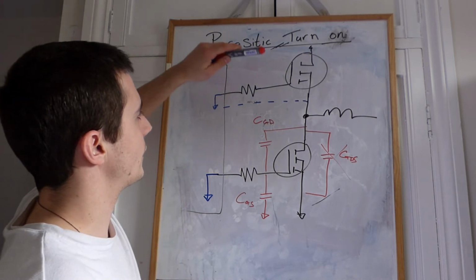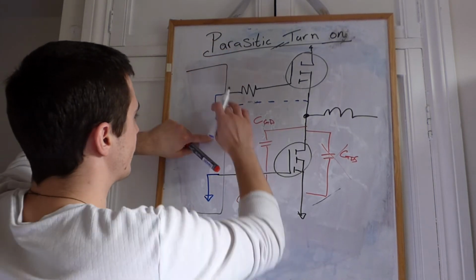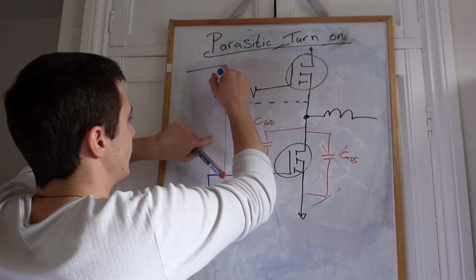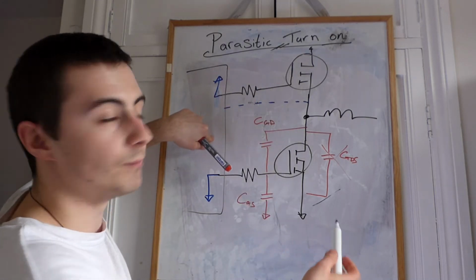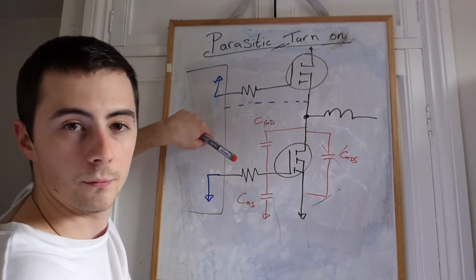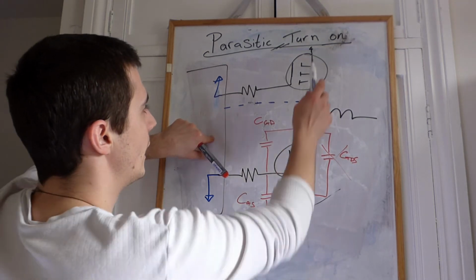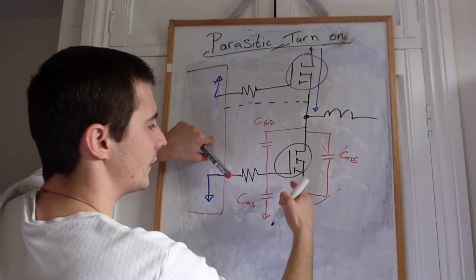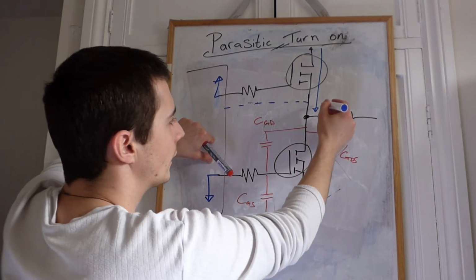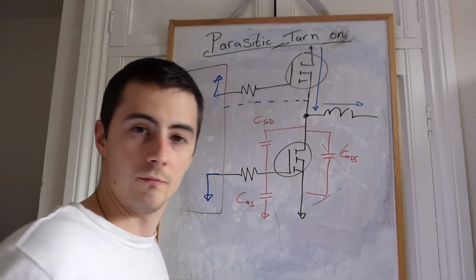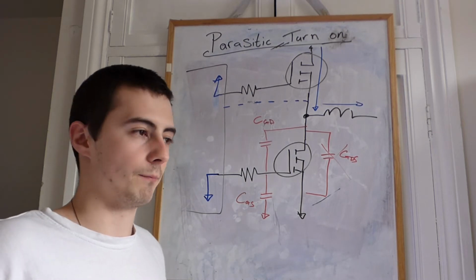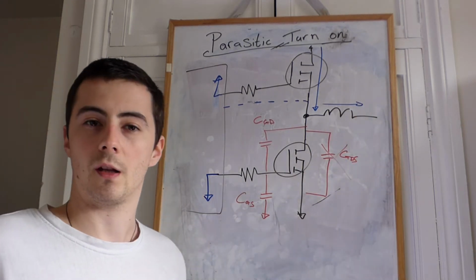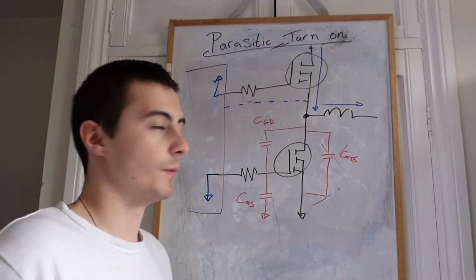So let's say that we're going to turn on the high side MOSFET. That guy, for all intents and purposes, is connected to the power supply positive voltage. This guy turns on, we get a current flow through here. This guy is currently off, so current goes that way, and that's how you drive some circuit like this, okay? I'm sure you guys are familiar with that.